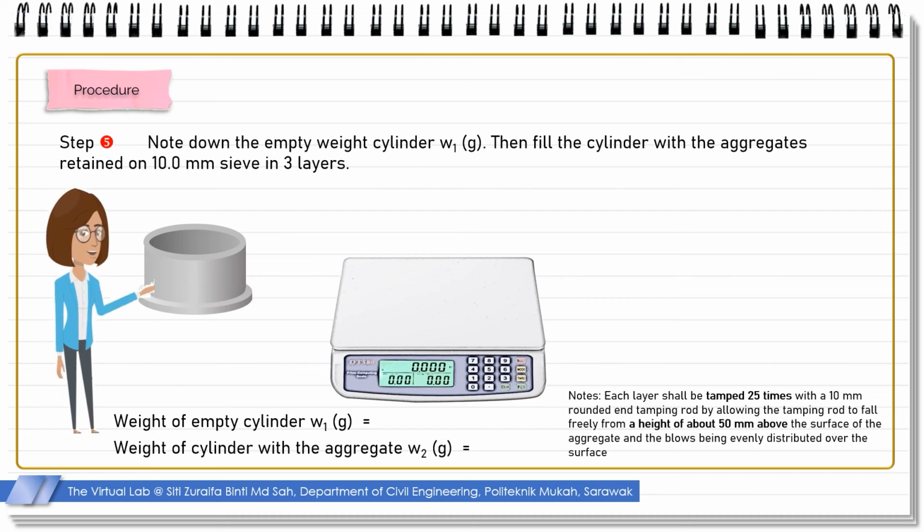Remove, by rolling the tamping rod across and in contact with the top of the container, any aggregate which impedes its progress, aggregate being added to fill any obvious depressions. Weigh the mass of aggregate in the cylindrical metal container, W2. Determine the mass of the uncrushed sample alone as W3, in which W3 equals W2 minus W1.